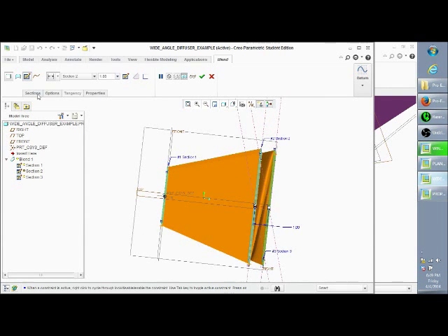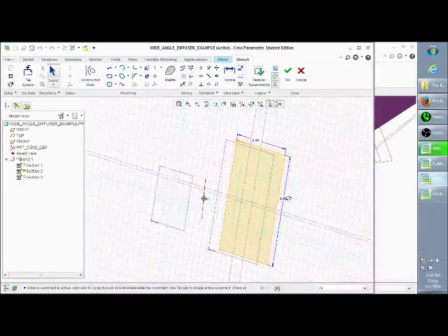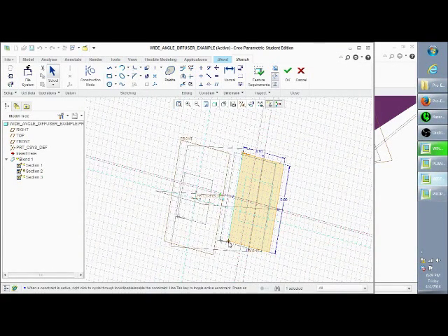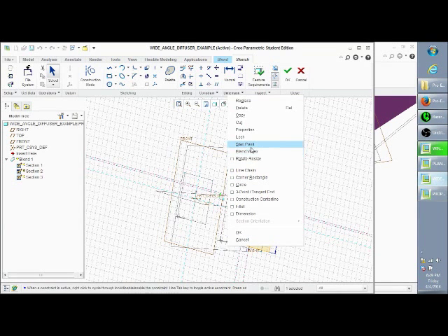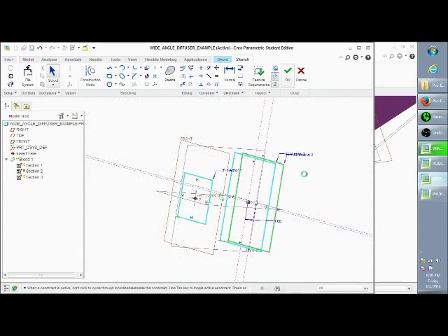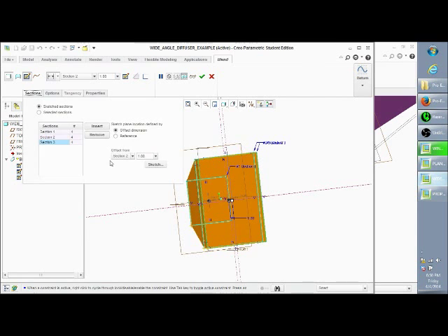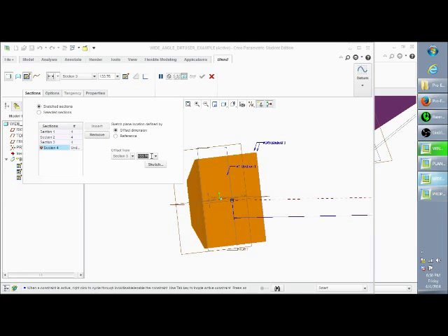What I did there was start from the wrong section starting point. I'm going to edit that so it's actually starting from the right one. If I right click at the point I want, which is a hold right click, not just a simple one click, and then click the select point to change it, that should do it. Now I'm going to go ahead and create another one, and this one will be offset by 5.75.